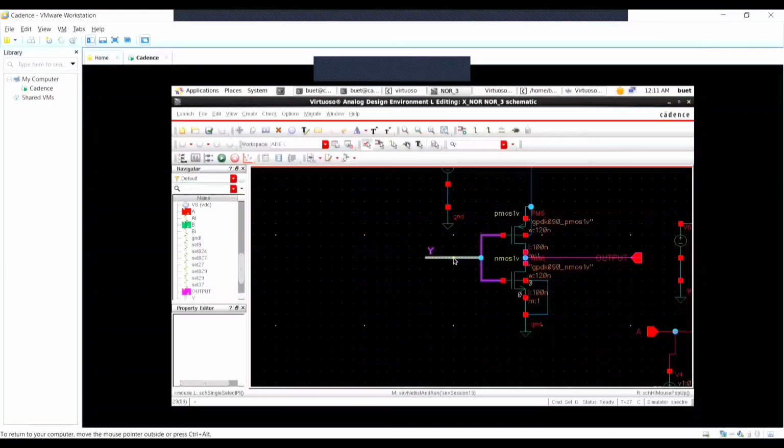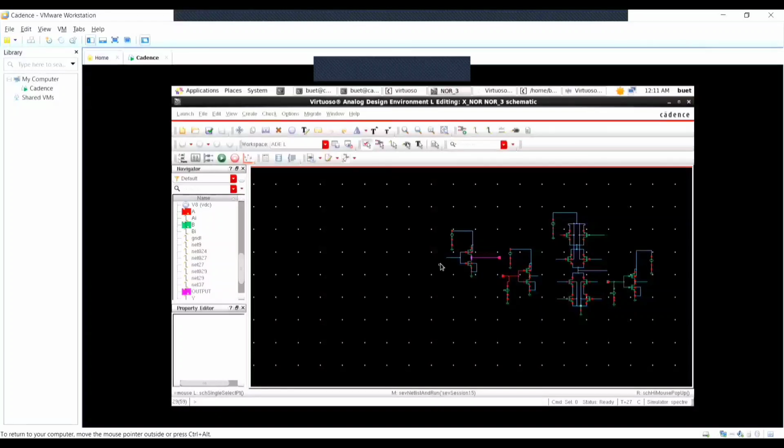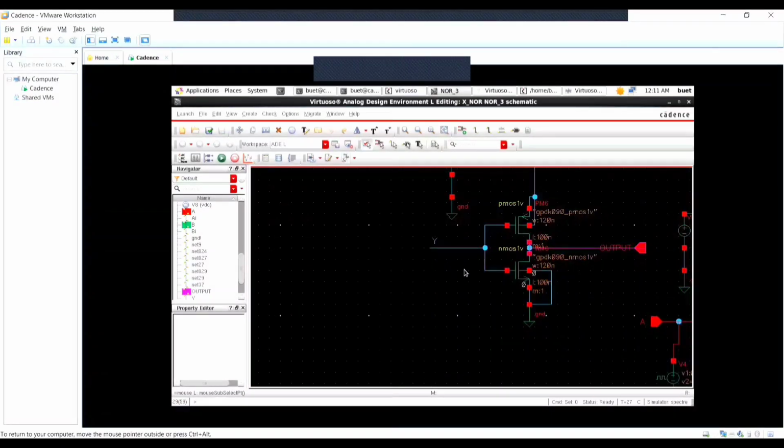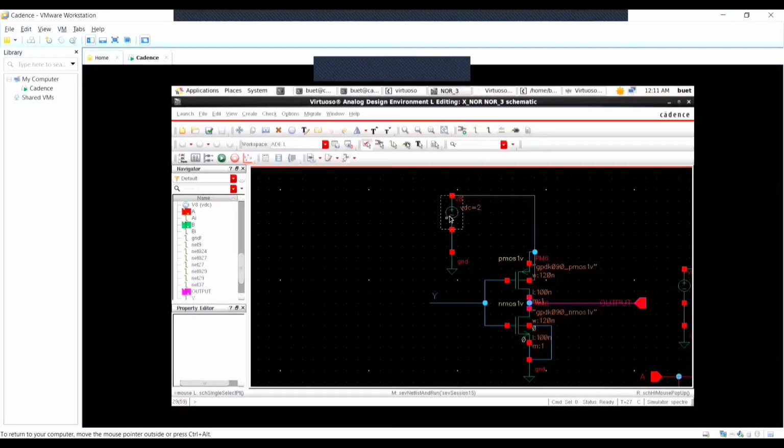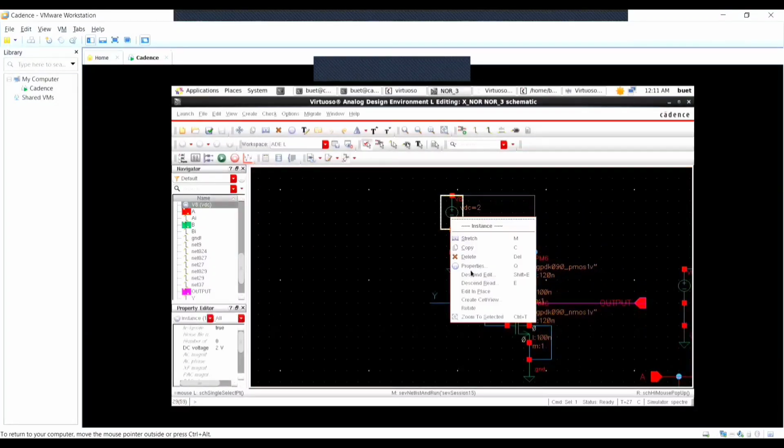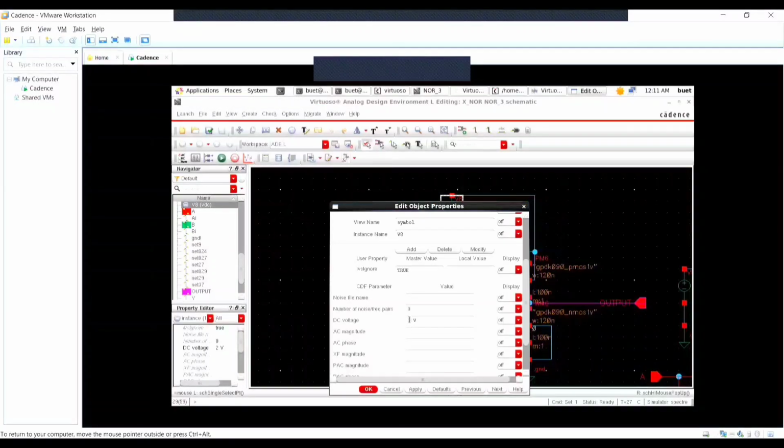So this is actually the input, and it is connected to, if I touch this wire, you can see the main wire lighting up. See, this is lighting up. That means they are both connected. So it doesn't need any source. So I've deleted this source. My video suddenly stopped, so I couldn't show you. So this doesn't need any source, and this is the output, our main output. And in this voltage source, you are going to set 2 volt. I've set 2 volt. Okay.